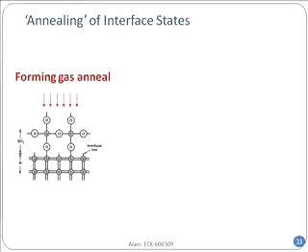Now, what is generally done in this case, if you have a lot of dangling bonds on the silicon surface, is of course the first thing one would do is to bring down the silicon dioxide. And this is the flattened version of the silicon dioxide, where you see the silicon nestled between four oxygen atoms, and every oxygen being shared by 2 silicon. That gives you the formula silicon dioxide, because silicon gets half of the 4 each one, and that's why it's SiO2. Now, what you can do then is do this anneal.